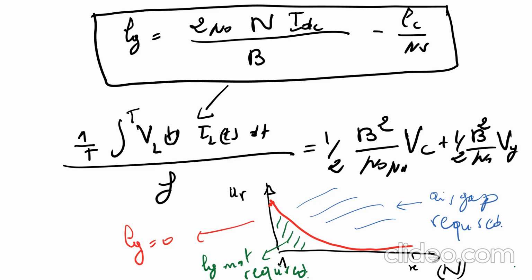So as you can see here, all those inductors are poorly designed, because from this equation we understood that there is only one unique air gap, and that will give also one unique inductance for a given magnetic core that has a given number of turns and will be used to handle a specific current.